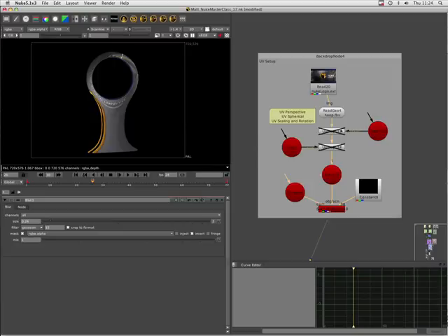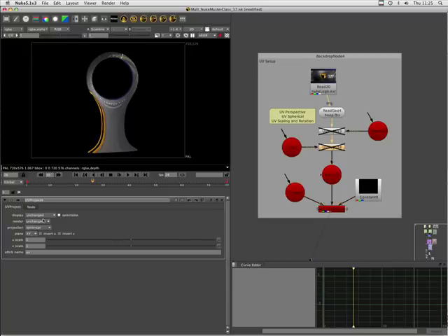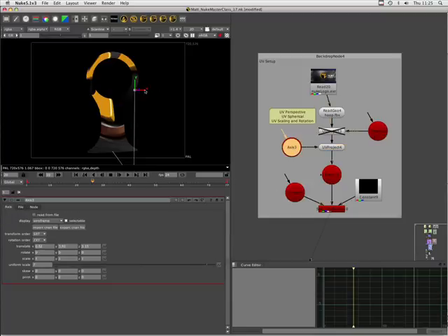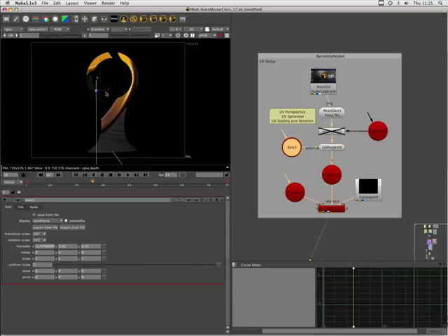Now what we can do is use the UV projection system to add UV data onto the geometry. And there's lots of different ways that you can do this, just like you would in 3D. You have the ability to do it as a perspective or a planar. You can do spherical or cylindrical UV projection. So if I add the cylindrical one, so we just change this to cylindrical, as I move around this axis you can see that we're basically changing how that UV information is applied. We can even go as far as to rotate that, and you can now see really clearly what's going on.